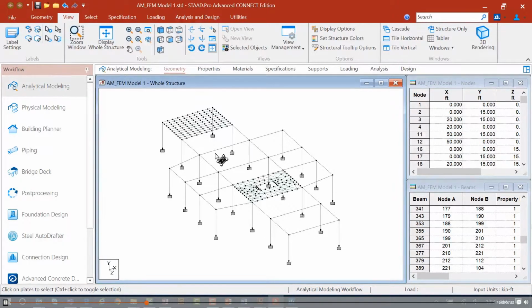In addition to that, if my overall goal is to create a slab over this entire area, I'm also going to want to pay special attention to the number of divisions I have along each side as I create additional or adjacent bays, because again, I want the plates in this bay to coordinate with the nodal locations in the adjacent bay. So a little bit of extra planning will be needed. Now, this may be, if you have a very large area, slightly time consuming.